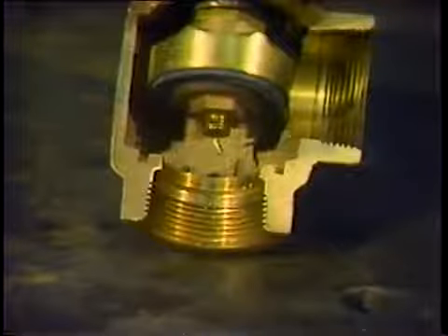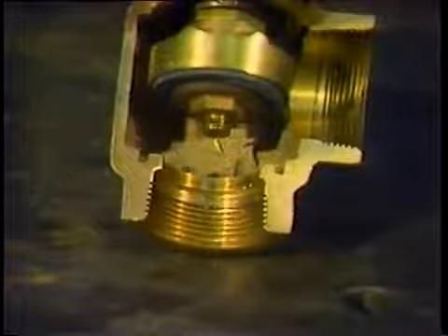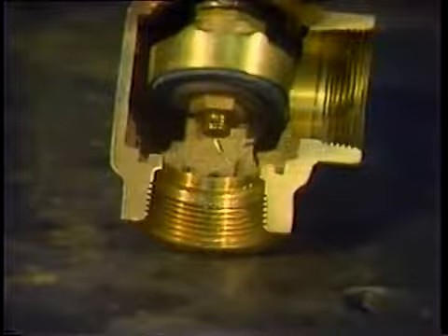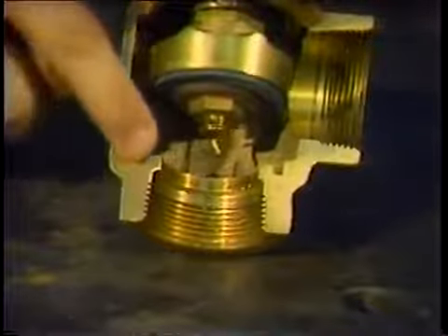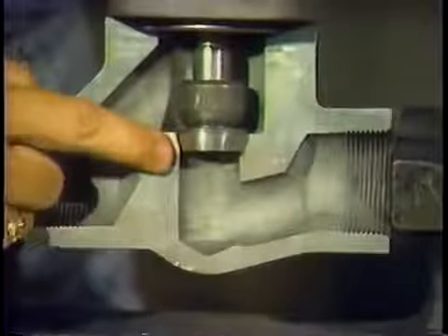The materials used in constructing a seat will vary depending on where the valve will be installed. For low pressure, low temperature systems such as service water, the valve seat may be made of bronze or a Teflon type material. In systems requiring high temperatures and pressures, the seating area must be very strong. Stellite, a commercial name for an extremely hard metal, is often used. This metal has proven to be highly resistant to damage due to leakage of steam. The disc is the part of the valve that presses against the seat to stop flow.